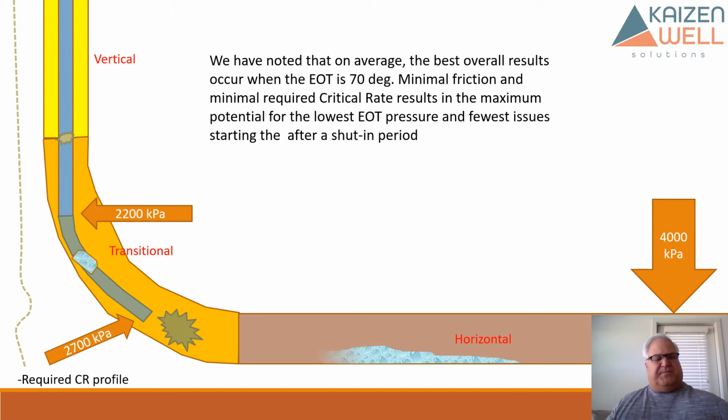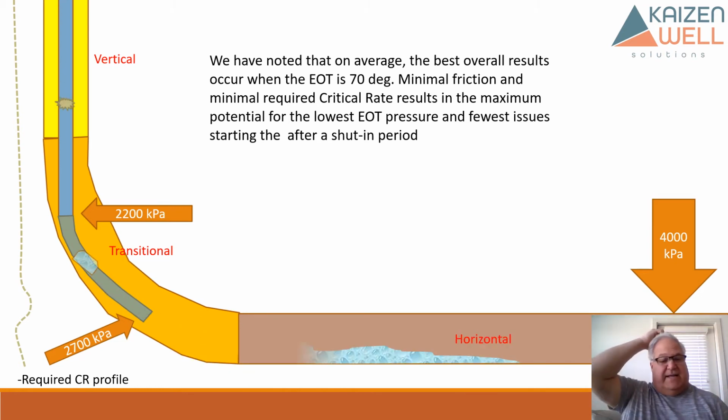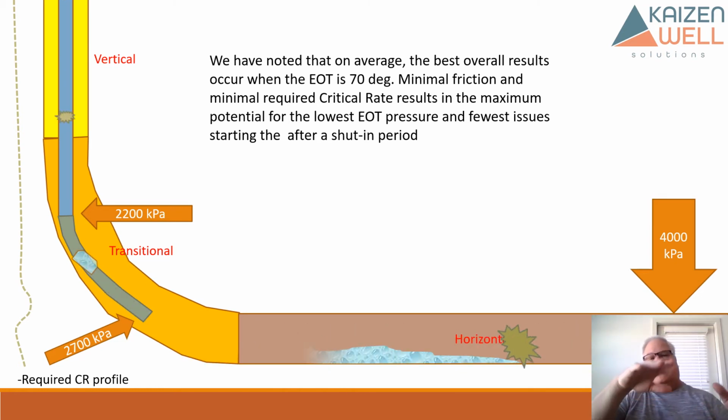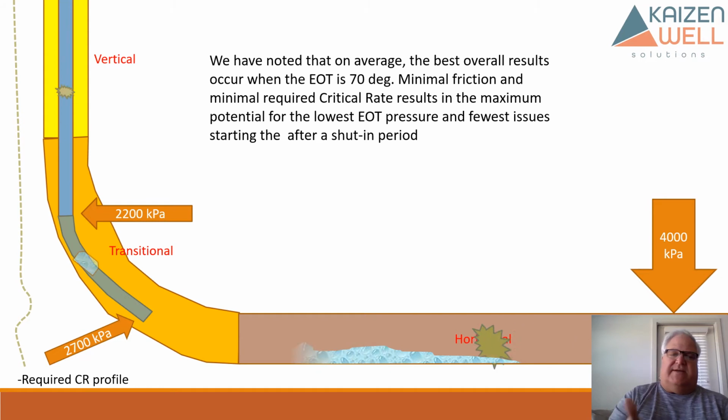When the fluid that's entered the tubing moves out of the way, of course, the energy that pushed all that fluid there is going to go up the tubing as well, and the pressures are going to drop, and then the fluid that didn't enter the tubing will start to drop, and it just keeps repeating the cycle. So you have this very, very active area right in here, and you also have all the churn flow and all sorts of other things going on that can create a lot of liquid fallback.